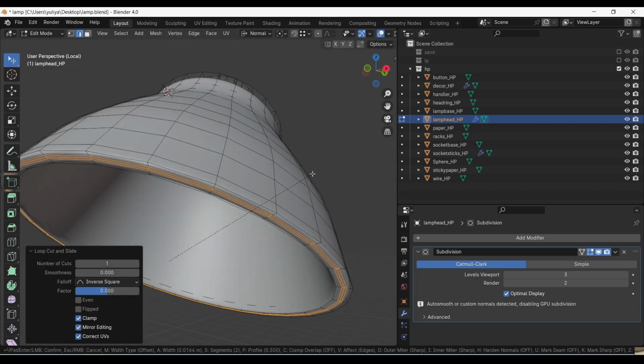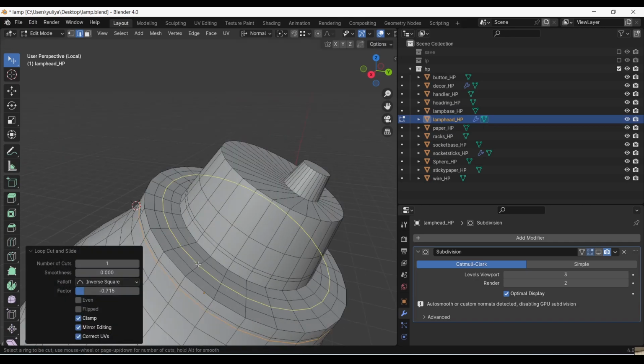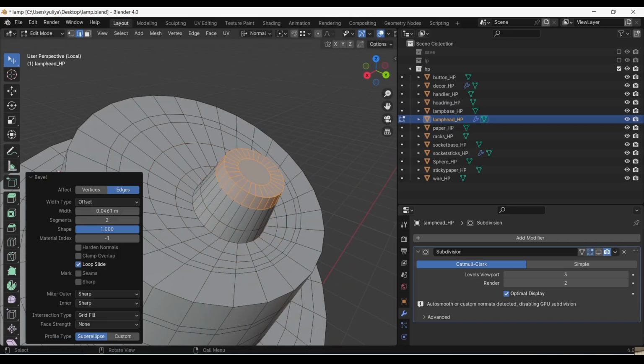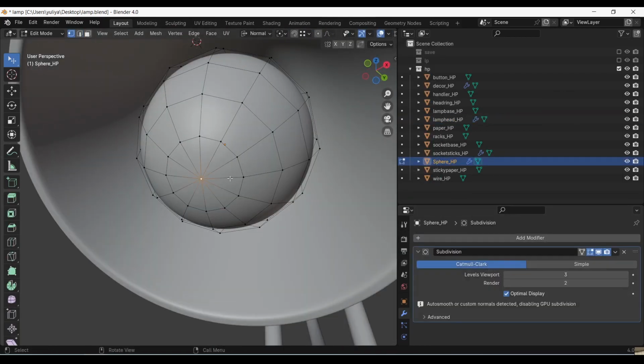Next, I start creating a high poly model based on the draft. Correct shading is important here and therefore a good mesh net. It's important not to lose the shape of the object but not to make the edges too sharp.